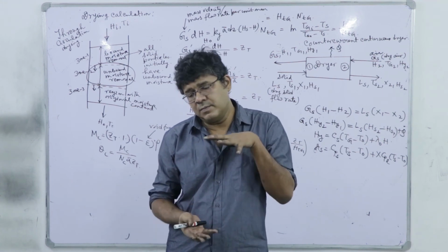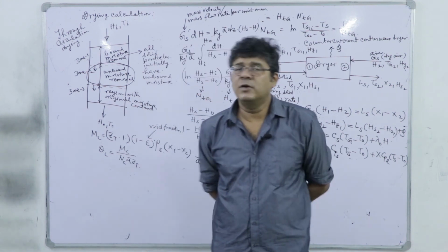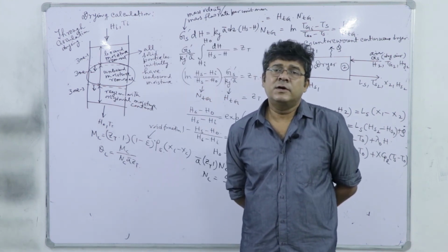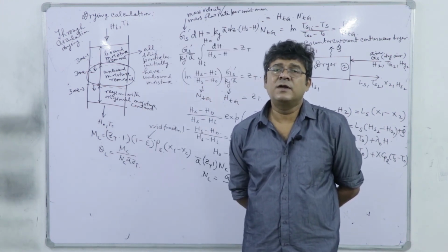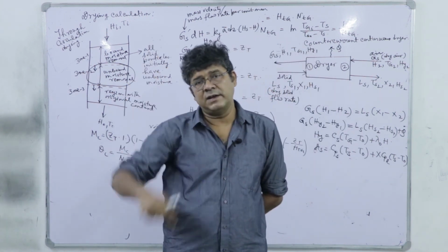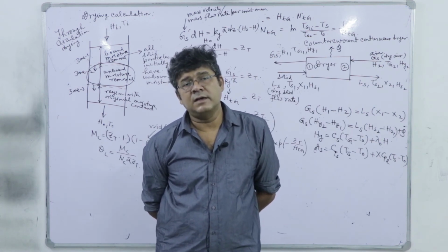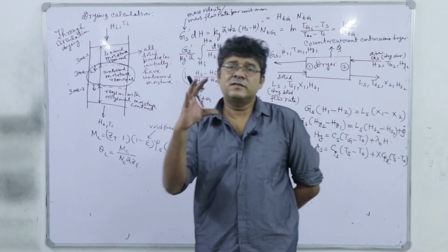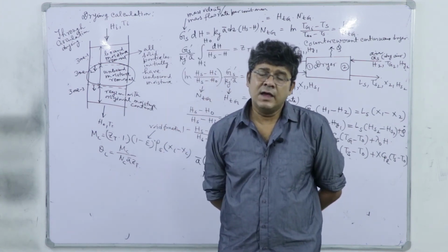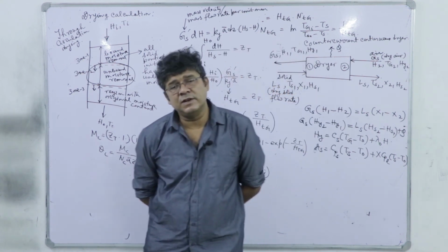So though the bed may operate initially, the entire bed will undergo this unbound moisture removal, right, but unbound moisture will be removed after some interval of time. So the topmost region of the bed, if I have a delivery of air from the top, will be now undergoing after some time this bound moisture removal stage, whereas the latter stage will be the unbound moisture removal, and finally when the air will be saturated, the moisture content will be same as that of initial.